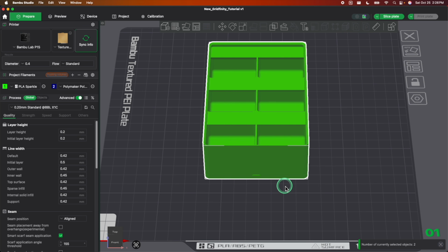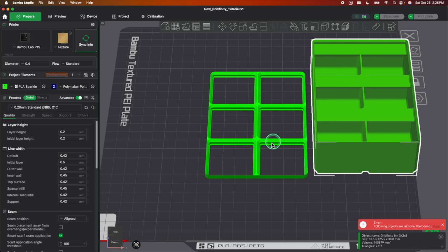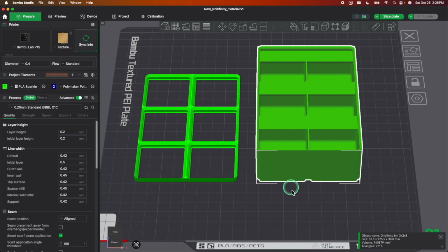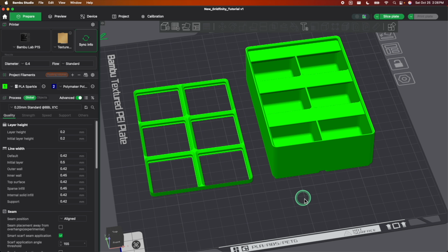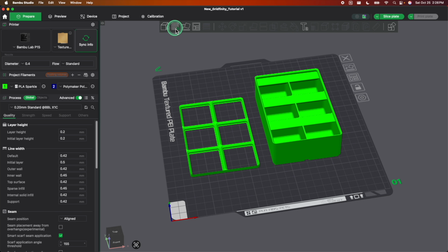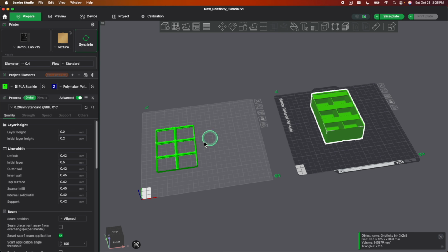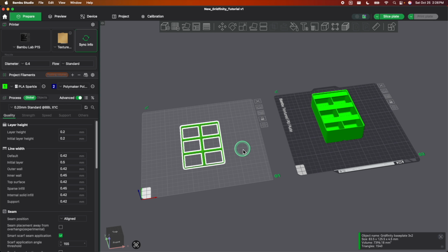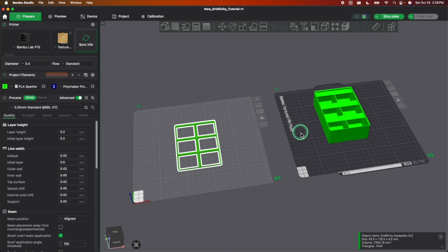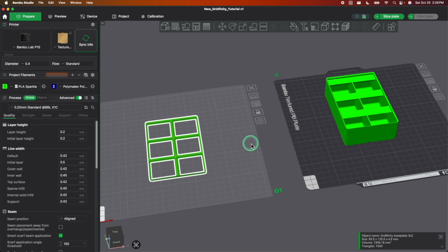We popped our parts here into the slicer. And if you're unsure, you can move one out of the way, put one over here, one over here. So if you're feeling really crazy, you can print both of these together. You can set up your different build plates. You can send them to a couple of different printers at the same time to get mocked up. But it's a really seamless process in Fusion to take this part that you just created in whatever the 20 or so minutes that we were talking about it and get it sent to your printer so you can go ahead and slice it and send it off now.